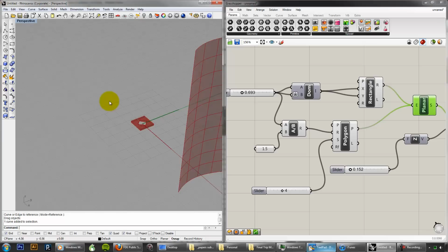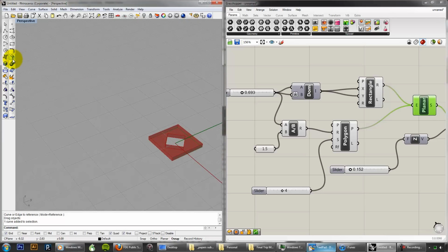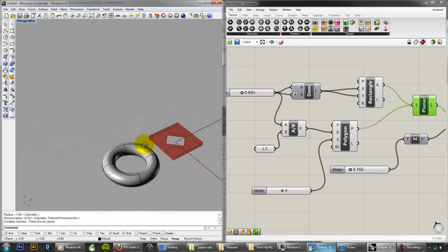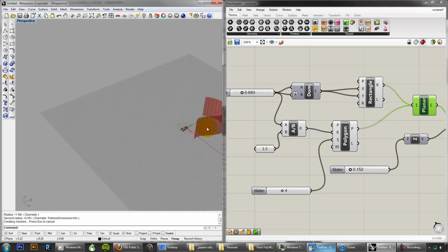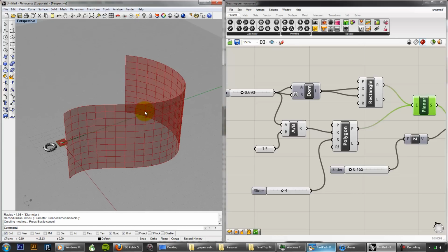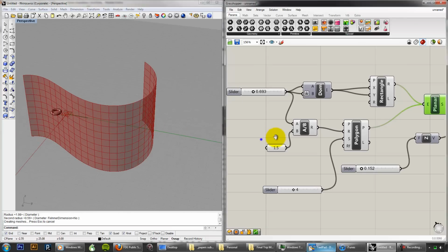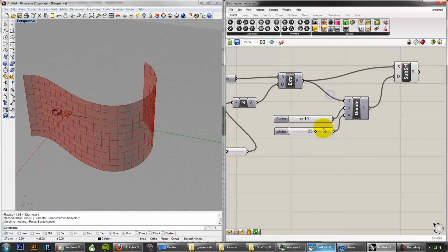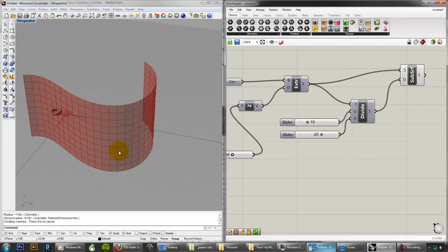Okay, the box morph works with any geometry. So it could be some geometry that I draw. So it actually could be a torus, our old friend, the donut. Could be a torus, or something that you drew. But the idea is it should fit into kind of a box in some fashion. And if it doesn't, it'll get stretched. And again, this is good for taking some geometry, like some of the systems that you created in your project, and adapting it over any kind of surface that you can get your hands on, and that you can tile up. So I can control the tiling here.